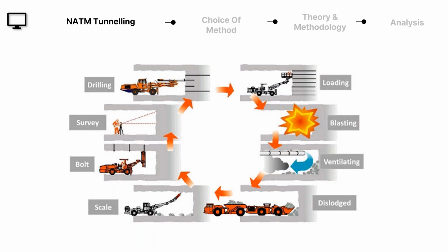After your drilling is complete, we will load the drill holes with explosives, let's say ANFO or dynamite or site mixed emulsion or site mixed slurry. Post loading and charging, the detonation will take place. Post detonation, the primary regulations state that the noxious fumes have to be cleared.